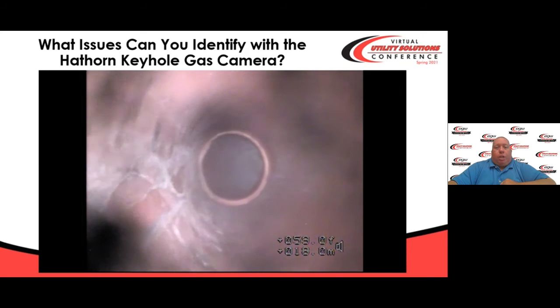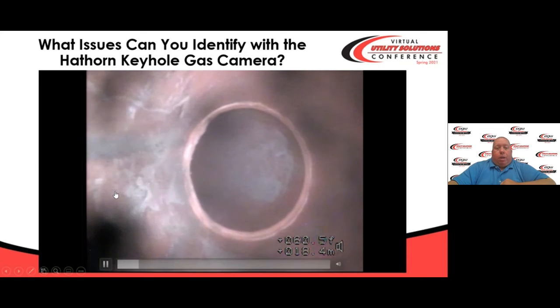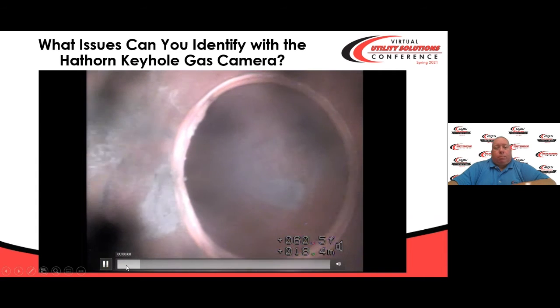Here we are approaching a butt fusion, and in my opinion, it looks a little bit suspect. Looks pretty uniform here, but here there's a strange edge, not very well aligned. This might be something that you want to drop an electronic marker ball at this point after you locate your sonde and come back and inspect it from the outside.